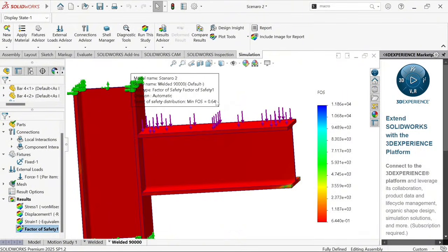By default, any product out there should have a factor of safety of at least 2, right? So most people even raise it to 3. It depends on how critical the part is. For aerospace parts, the factor of safety goes as high as 7, because there's extreme temperature and a harsh environment, right?